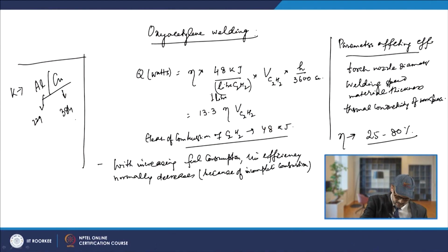For aluminum it is 229 joule per meter per second per degree C, and for copper it is even higher, 384 joule per meter per second per degree C. For other materials, steel is near 41, Inconel is even smaller at about 18, and for titanium alloy it is 27.